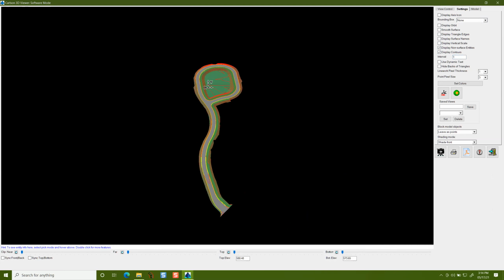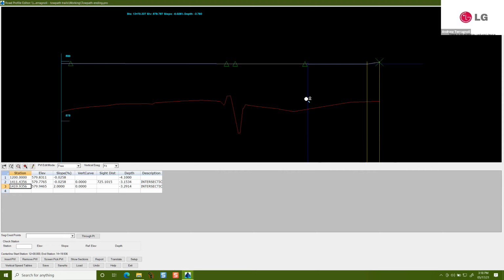The whole thing that was driving this was the floodplain elevation, which was 576.8. If you work backward from the lowest finished floor elevation at 578.8, because there's a minimum of 2 feet to cover, and you work your way backward toward the center line of the road, I think 578.3 or something was the lowest I could get that center line of road in order to keep the finished floors above the floodplain when we elevate lots, or rather when we elevate pads.